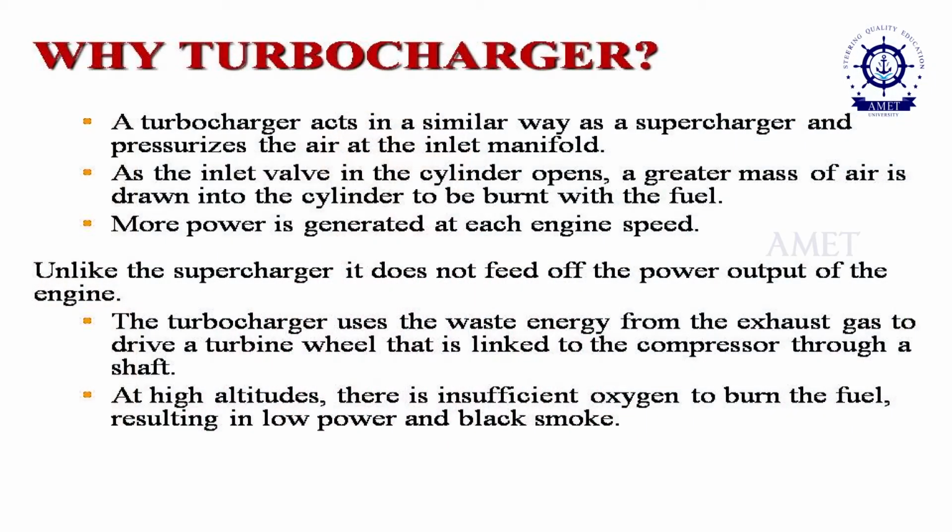That is one method. The other method could be, I can have the engine, and from the engine's crankshaft I can have a gearing system. The gearing system can run and then it will drive a blower, and I will be able to add more air. That is another mechanism which is possible.